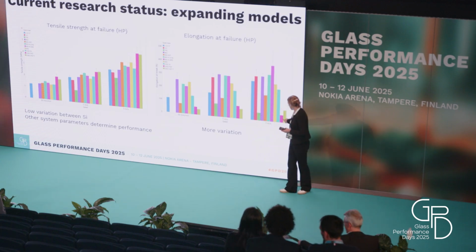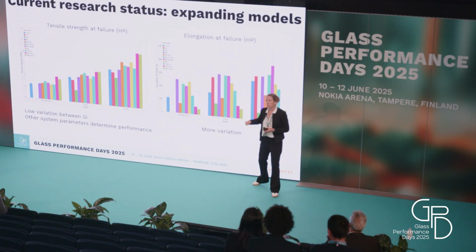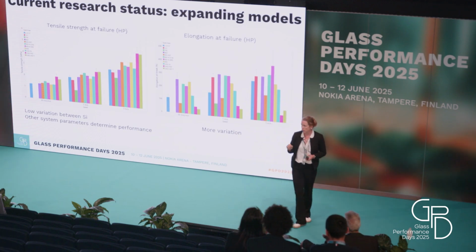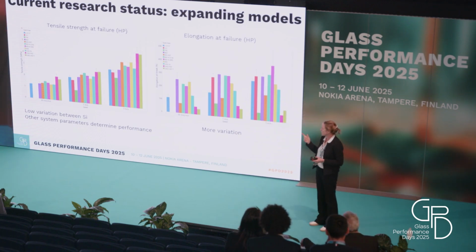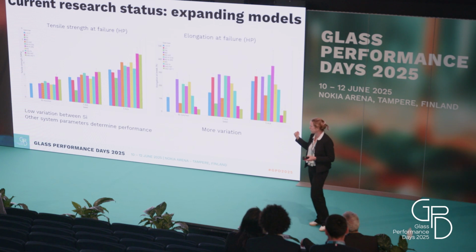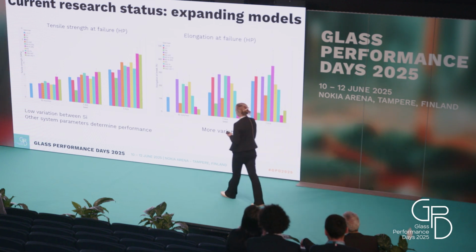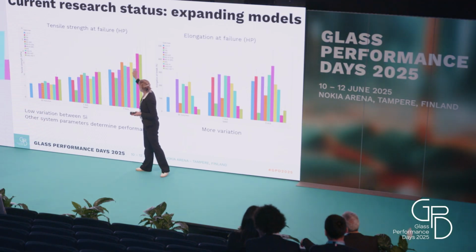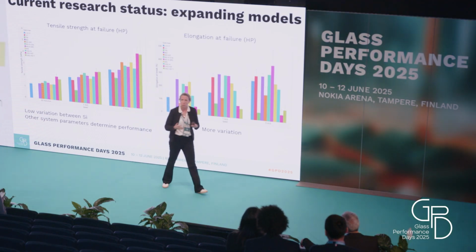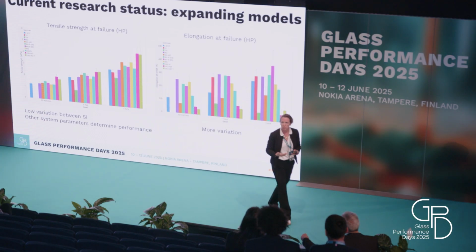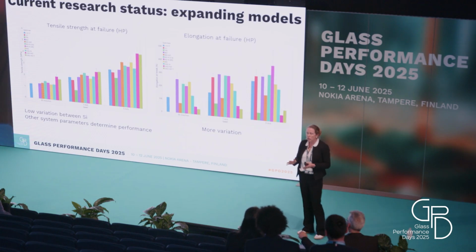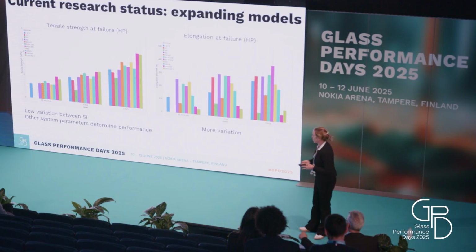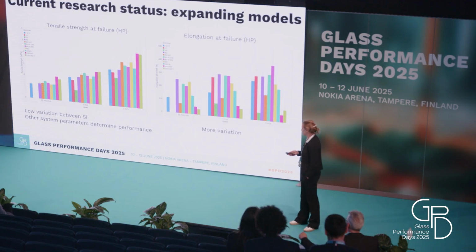The two on the right, every time, are the 3363, so these are not SG, structural glazing, but IG, and that's why you see these big differences. Interesting to note is that at high speed, we don't see that much difference from material to material, these two excepted. And when you go to simplified approaches, we could probably not really consider the silicone specifically. For a simplified approach, it doesn't make a big difference which material you're using here.